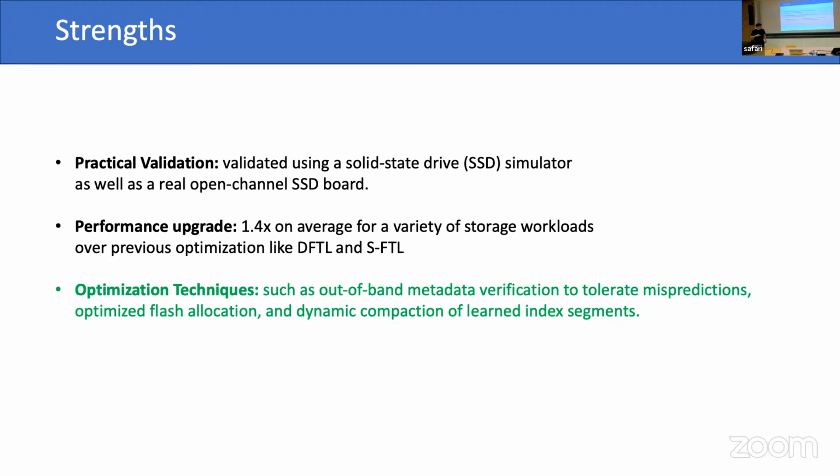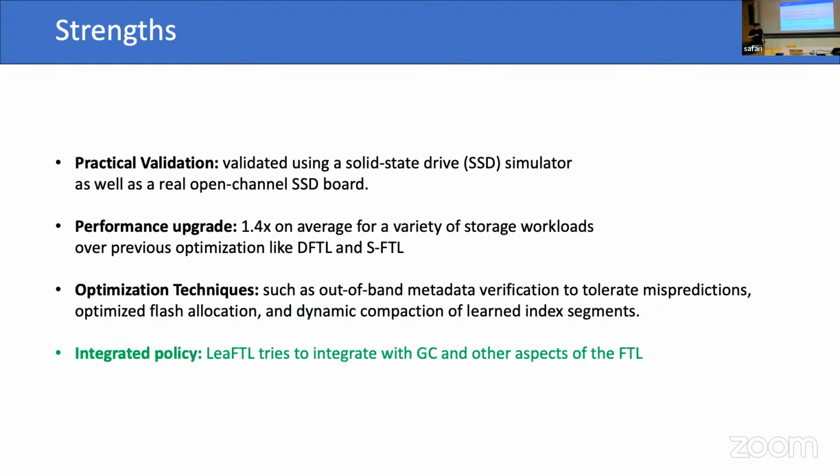And using out-of-band metadata to verify misprediction or dynamic compaction to reduce the size of the log-structured data, I think it's really smart, and it keeps it quite simple so that we don't incur too much overhead. And also, although I have not talked about it a lot, LeaFTL integrates really well with the core FTL functions and with the garbage collector.